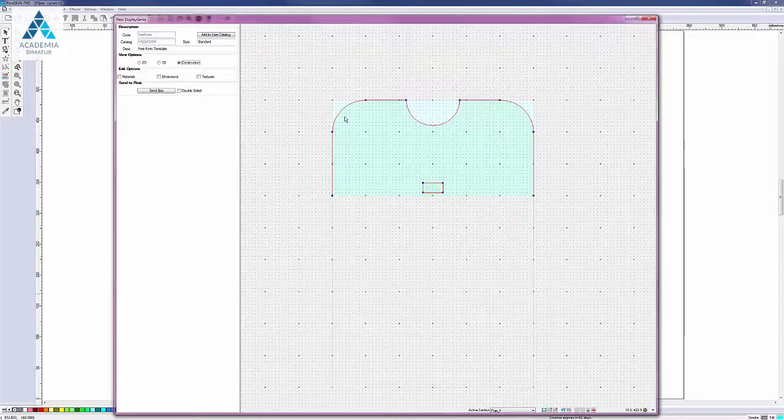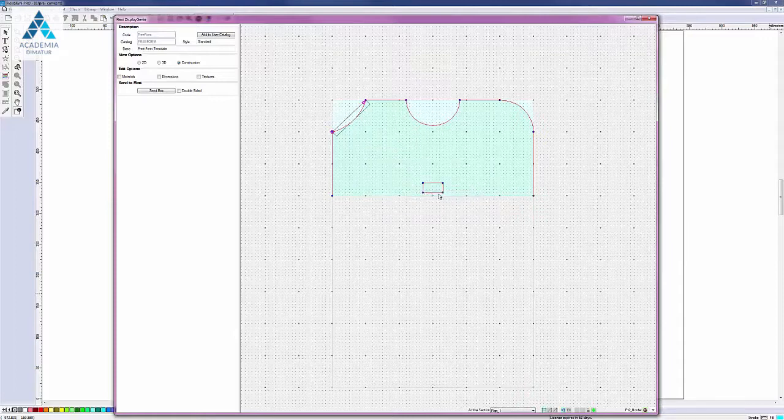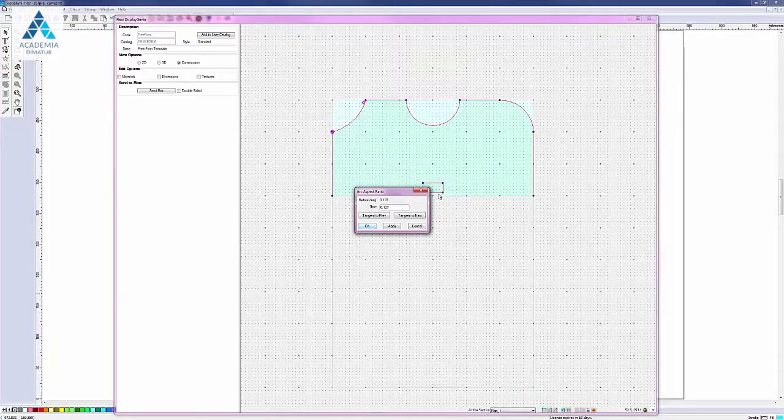Now if I was to change that curve something like this, then I can actually do that process of tangential fitting automatically. So I would say curve line, and now I press period and say tangent to previous, and as you see it goes to the tangential curve again. In this case tangent next gives me the same answer.